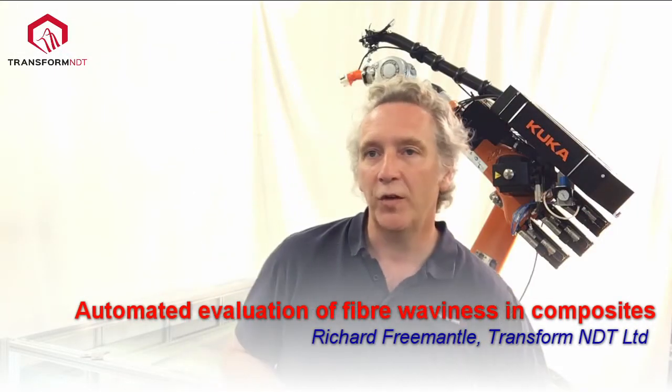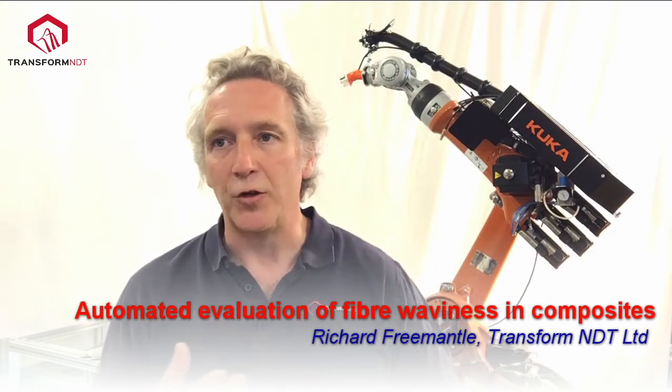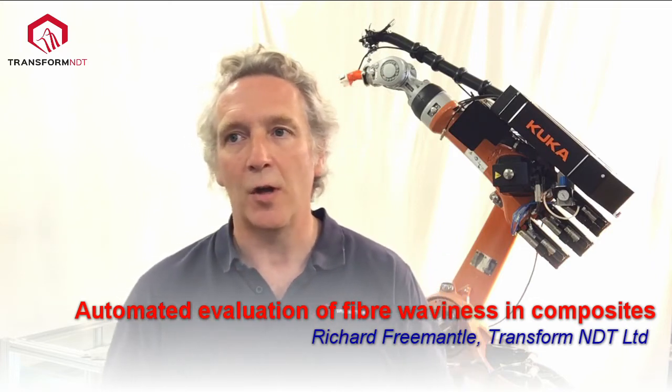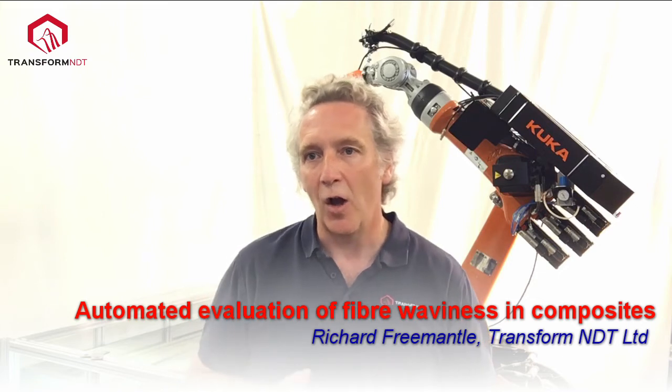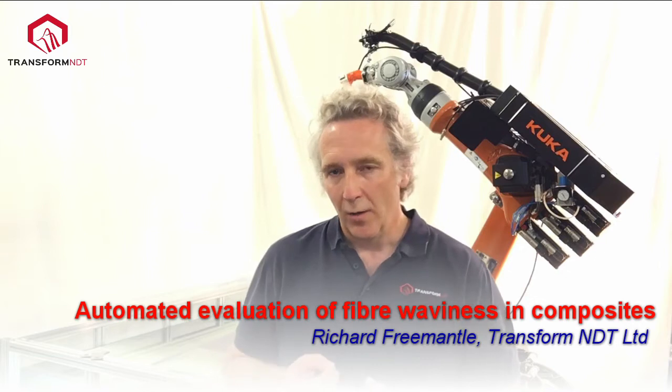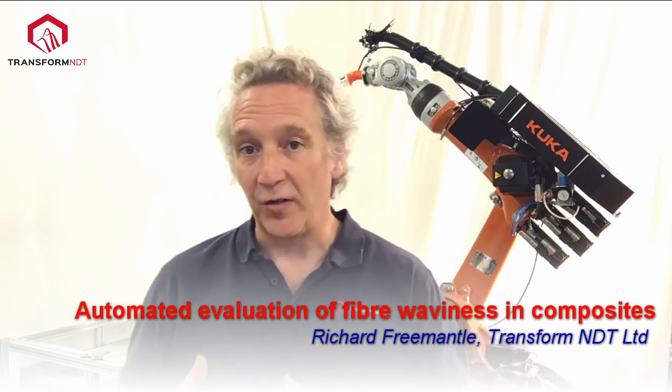So waviness in composites can occur basically where there's a geometry change. That might be where there's a ramp in the composite, or a thickness change, around radii and curves, or where there are reinforcements such as stringers or webs. Detection of waviness in composites is pretty difficult.